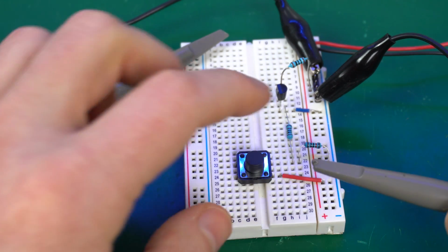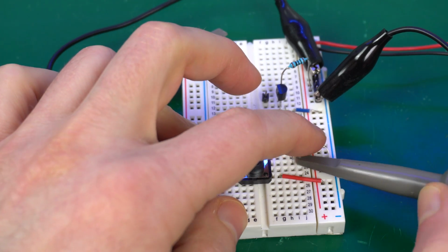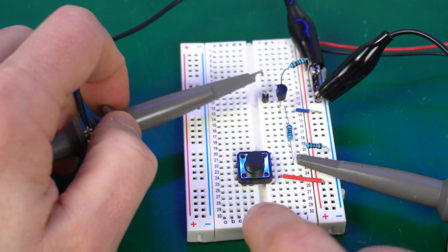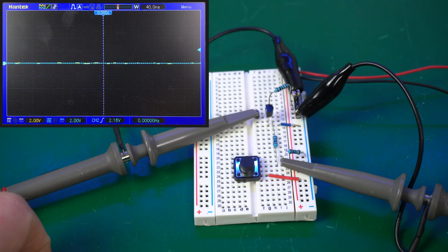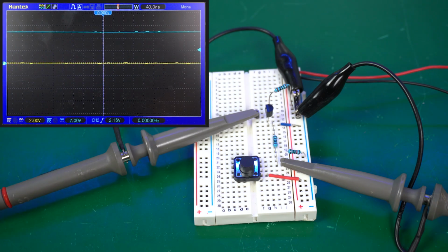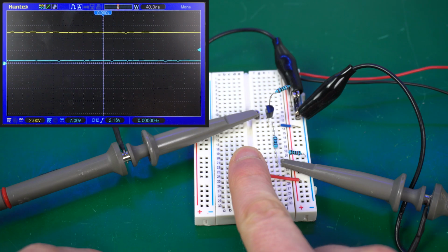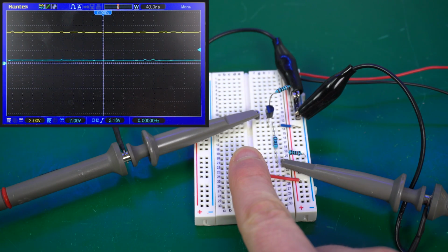So, like before, channel 1 is going to be the input, which is whatever we're sending with the button press, and channel 2, in blue, is going to be the output, which is the collector of the transistor. And as soon as I power it on, we get exactly what we expected, 0 volts input and pretty much 5 volts output. And when I press the button, input goes high and output drops down very low. Excellent. Okay, so the next step is to change the button to a real square wave.